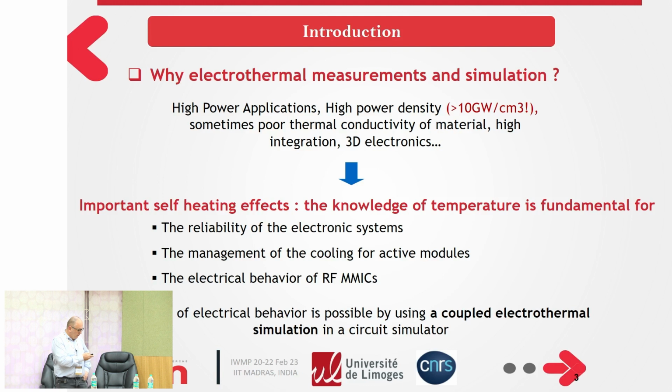Why? For the reliability of the electronic system first, the management of the cooling for the active module, and for the electrical behavior of the RF MMIC, as has been shown during this session. But the prediction of this temperature is very important, and then we can perform a coupled electrothermal simulation in a circuit simulator.